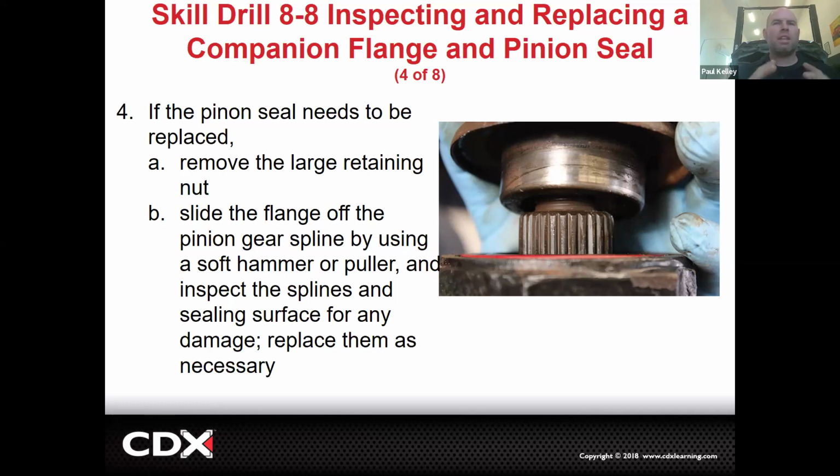Understanding that that big nut right there controls your bearing preload. What you're gonna do is scribe it, scratch it, make a mark where that nut is to where the pinion is. Then you're gonna take it out, do the seal, just like what Richard did. But you're gonna put it in, and then when you go to torque it, you're gonna turn it to where that line is, and then go the tiniest sliver more.